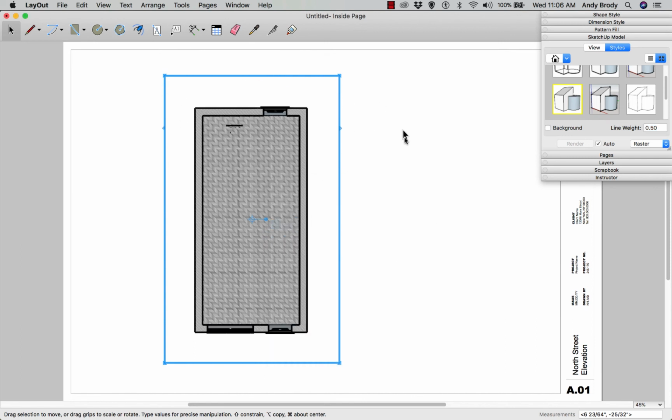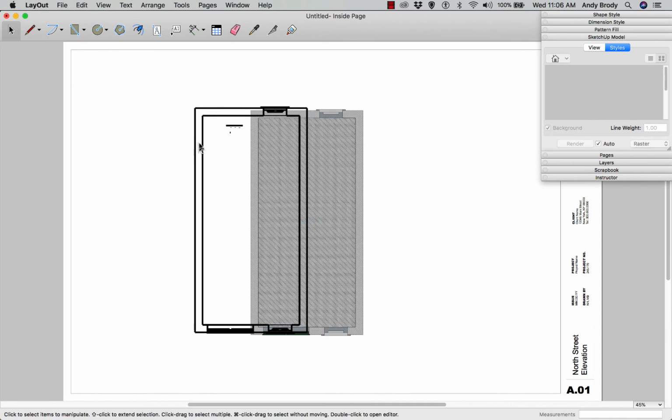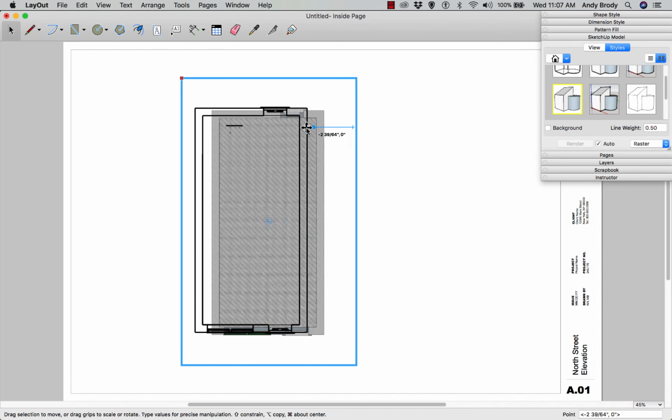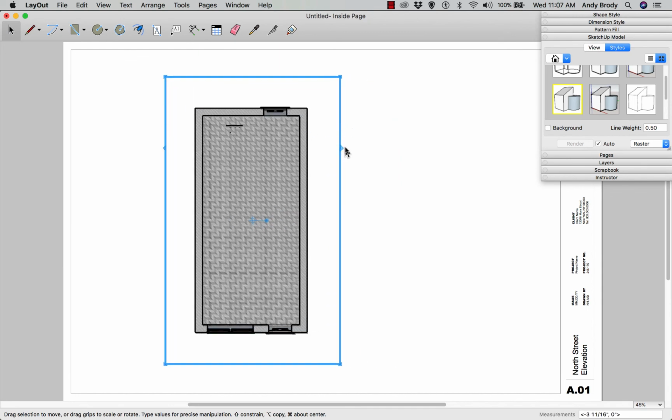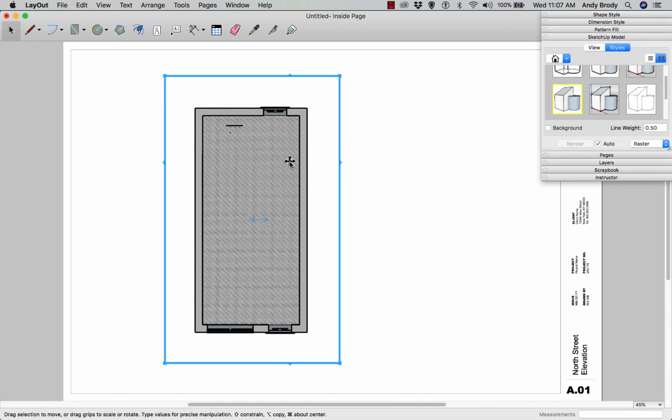And now what you see is I can start to really compose this view and the line weights that I want. If the line weights on the wall layer are too much or too little, I can tweak them to be exactly what I want. Absolutely, you could save a step and not have these two different layers. And in this particular model, I was successful at painting the inside of the walls a poché color. Obviously, that would save a lot of time, but you can do it either way. This technique will work better as your projects get more complicated.